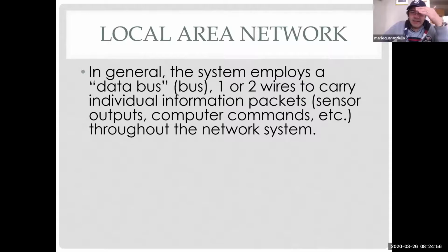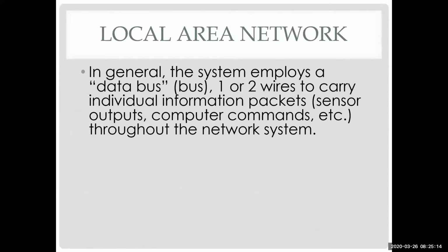It's like an indication, because actually it seems 1.8 to 4 something, right, if I remember right. What's the question? It's an indication of 5 volts, but actually it's like 1.8 to. Oh, yeah, CAN is a 5 volt scale, and we're going to get to that. They use a 2.5 volt bias, and CAN high goes from 2.5 to 3.5, and CAN low goes from 2.5 to 1.5, and they mirror each other. I got some good lab scope captures coming up.